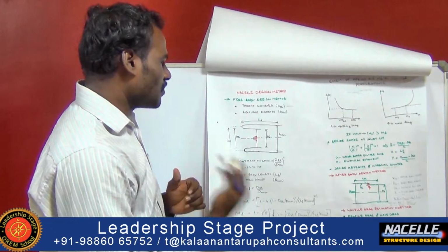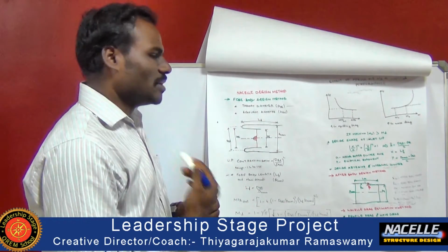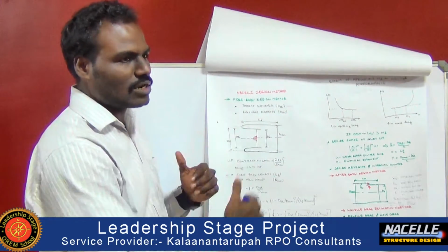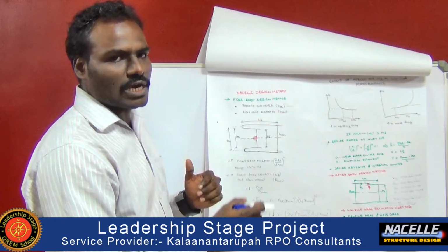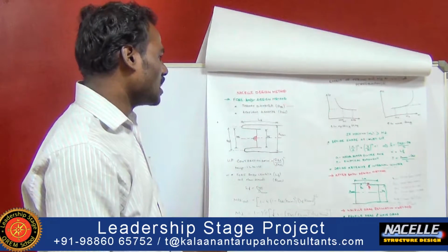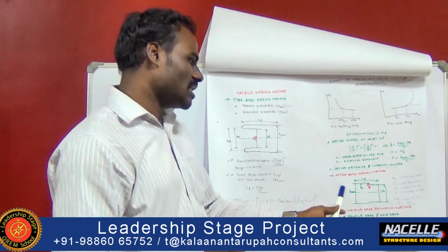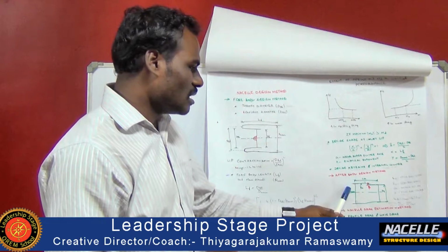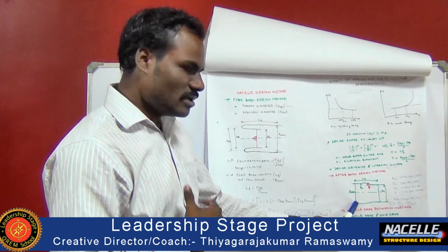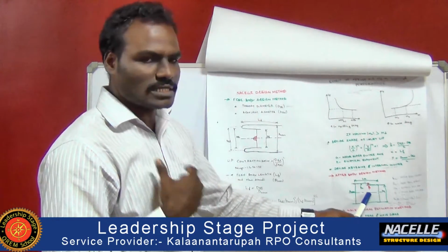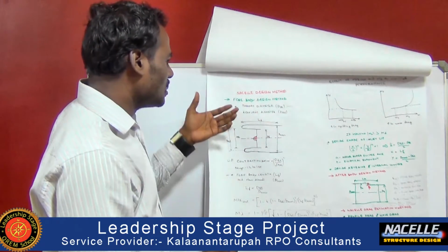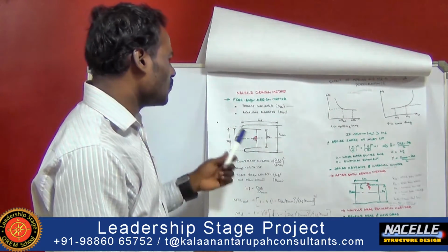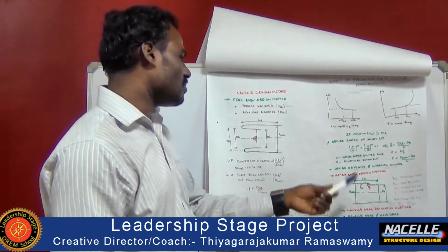The middle body design method deals with the cylindrical shape, the diameter of the nacelle, so we are not going to concentrate on the middle body design method. Whereas the afterbody design method starts from the outer diameter of the middle body structure to its thrust, that is the exhaust of the nozzle. The design procedure has to be carried out with respect to these three types: forebody design, middle body design and afterbody design.